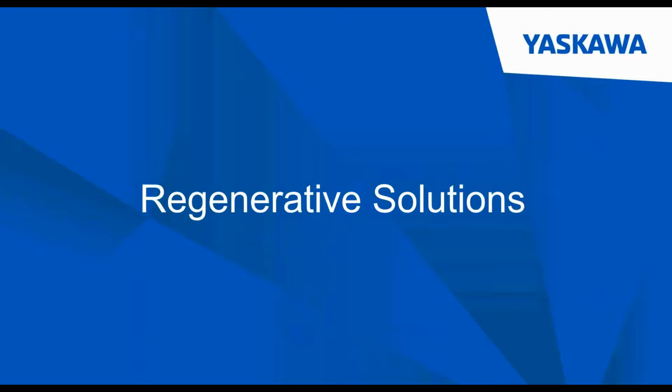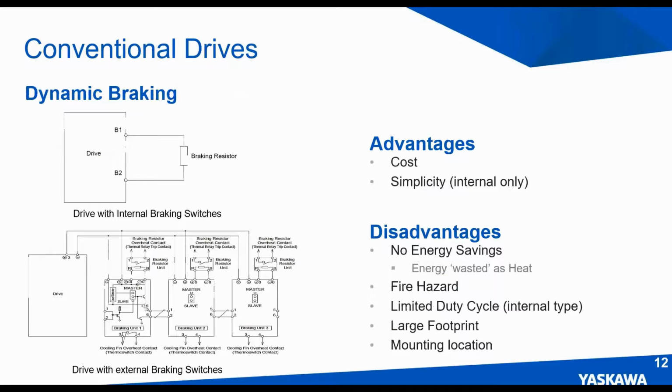So what solutions does Yaskawa offer for regen? Let's take a look. The most common method of dissipating regen is to burn it off using braking resistors. The advantage of this method is cost and possibly simplicity. Smaller drives have an extra built-in switch to divert the extra power to a resistor. Therefore, all you need with these types of drives is an external resistor to burn off that extra energy. A very simple concept. However, if you have a large amount of regen, or the drive doesn't have a built-in braking switch, then you need one or more external switches and resistors.